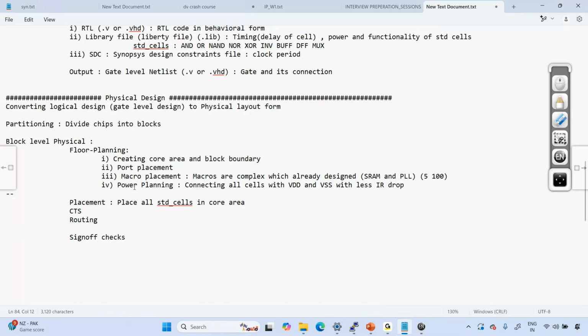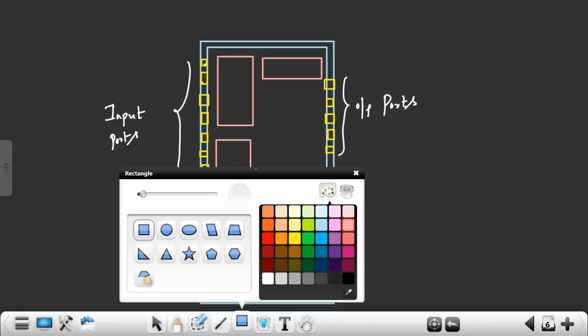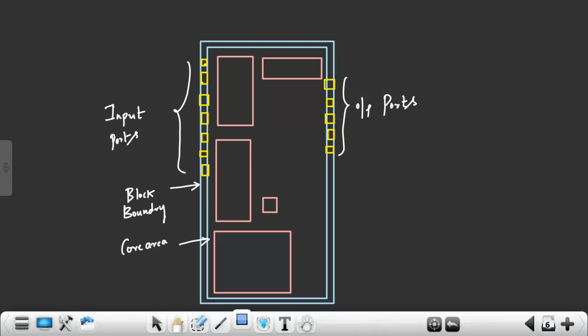No, decoupling capacitance also should charge, right? What is the role of decoupling capacitance? Whenever the voltage goes down, it is like your home UPS, right? The decoupling capacitance role is like a home UPS only. Whenever this voltage goes down to 1.2 volts, this decoupling capacitance will boost it. It will boost it to what? 1.5 volts. When it is boosted, the decoupling capacitance voltage will come down, right? Because this charge is gone. This decoupling capacitance voltage will come down to what? 1.2 volts. Again, it has to be charged.